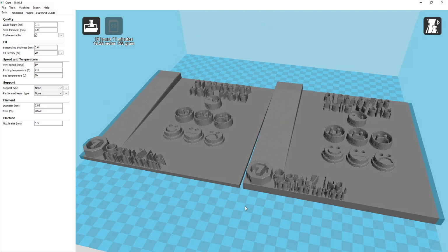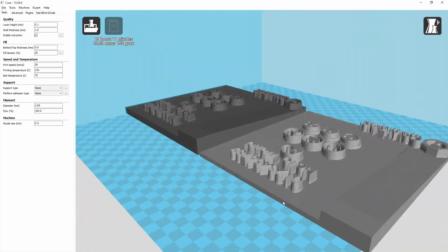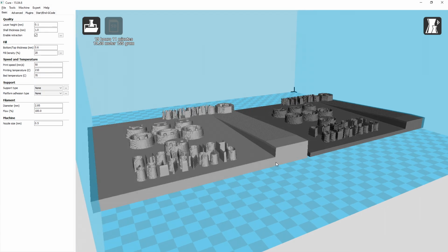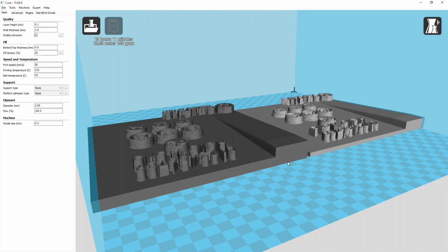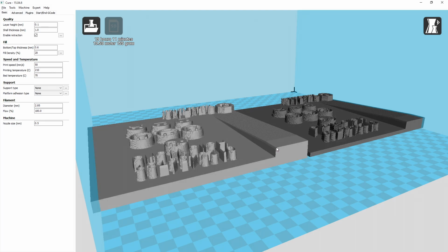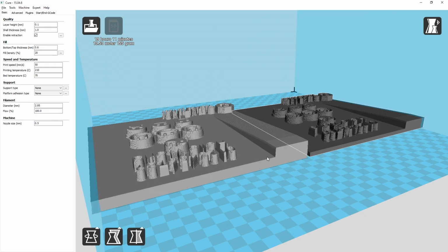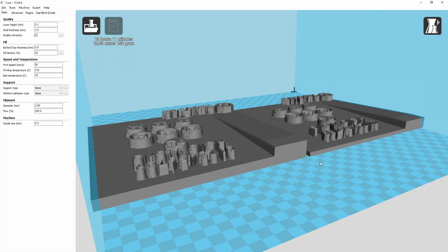So you can see now, it looks very similar, but I'm just going to orbit around this way so you can see a little clearer that the base, so now we have this base height here of 10, where this one we had a 5, so still 10 here, that extrusion from the base is still 10. So this one here with the base of 5, height of 10, total height of 15. This one, base of 10, extrusion height of 10, so a total height of 20. So 2 centimeters there, 20 millimeters.